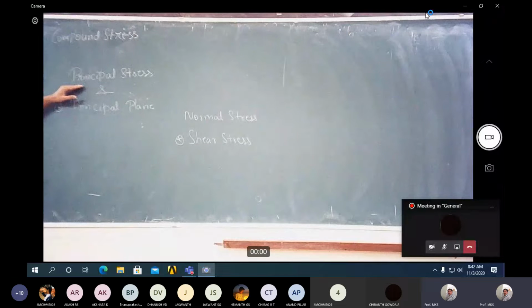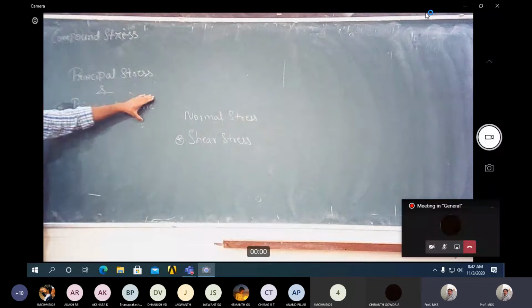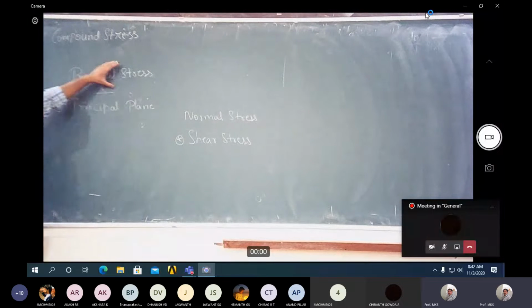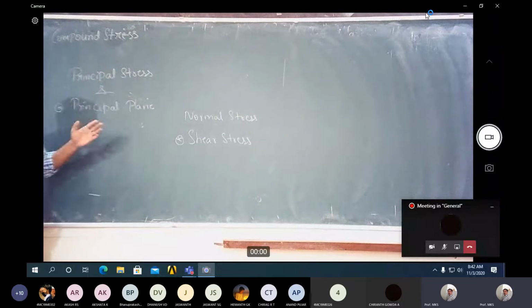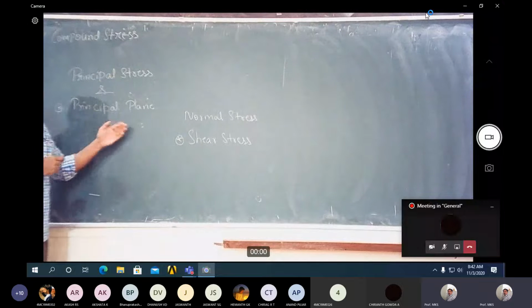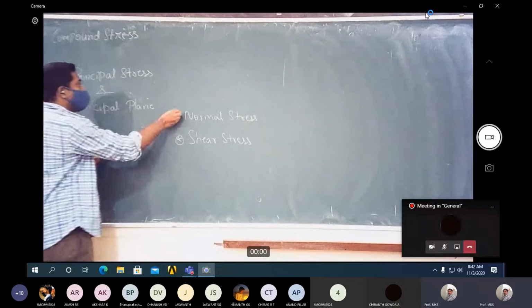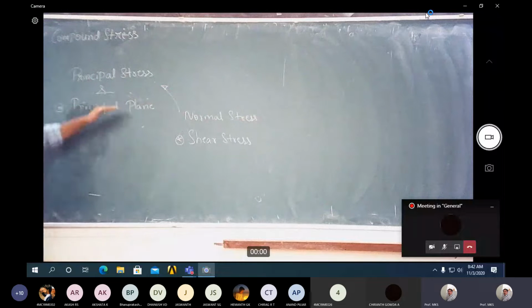Next, what do you mean by principal stress? In the principal plane, the shear stress will be zero, and there is only a normal stress. The normal stress acting on the principal plane, we call it a principal stress. Okay, that is the basic definition.